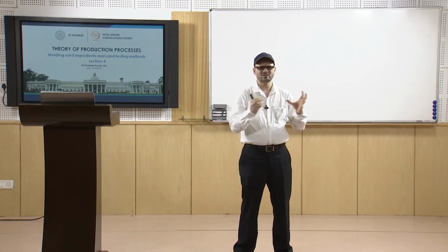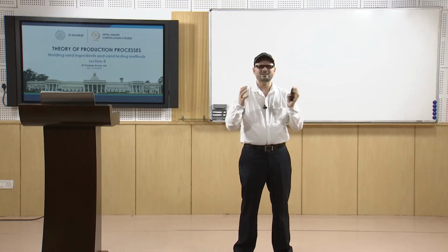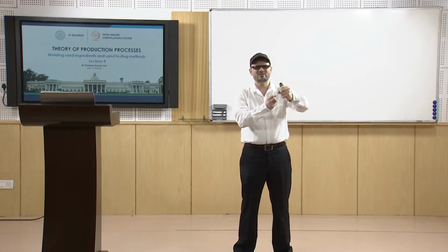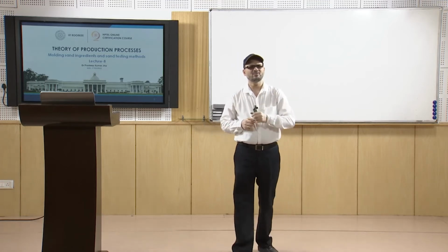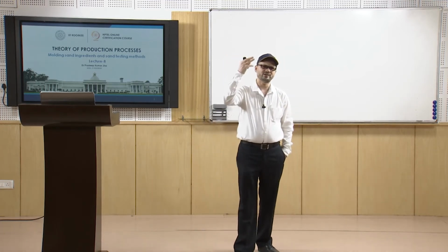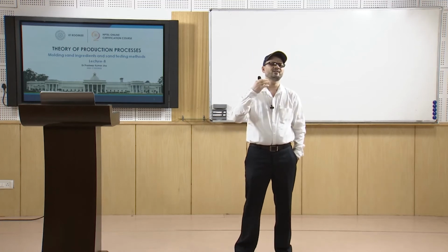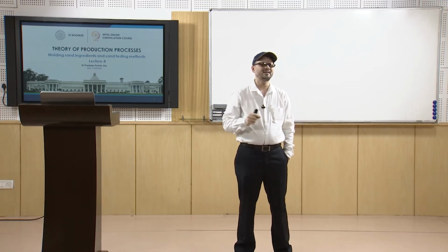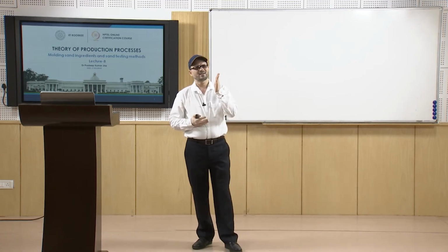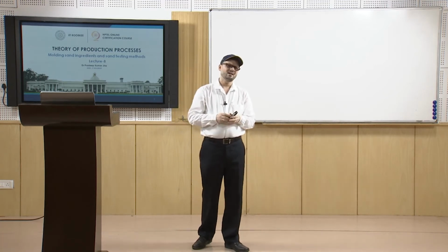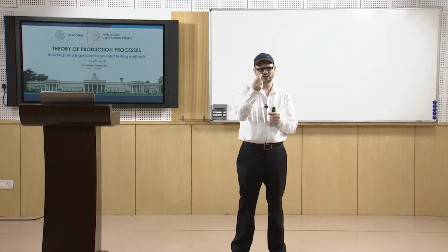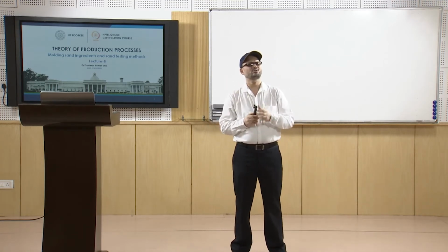Otherwise, if it is not following that casting during its shrinkage, it may tear. So, defects like hot tearing may come. We may discuss that when we discuss casting defects. This is basically achieved by putting certain additives inside the molding material. They will burn and provide a cushioning type of effect. So, that is known as collapsibility.